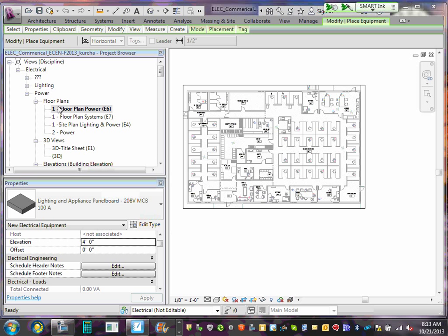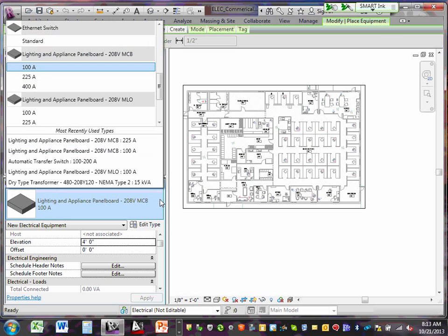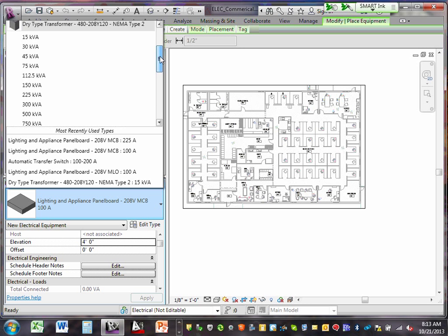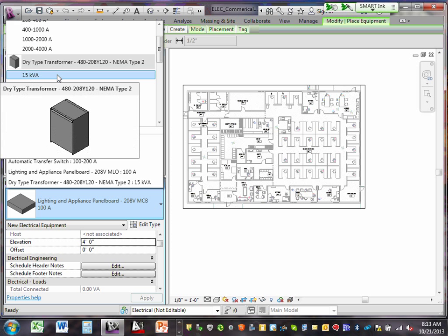Let's go first, one more time here. Click in it. Let's go all the way up until you find the transformer. Can you guys see that? Everybody get that? The transformer. Now, what size transformer do I need? We have a 500 amp panel times 208 times 1.73 equals.